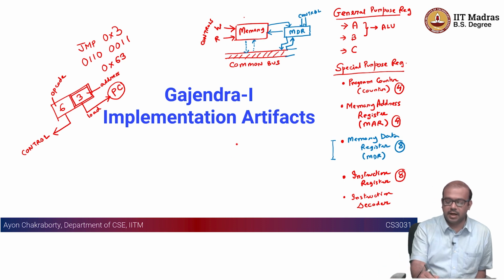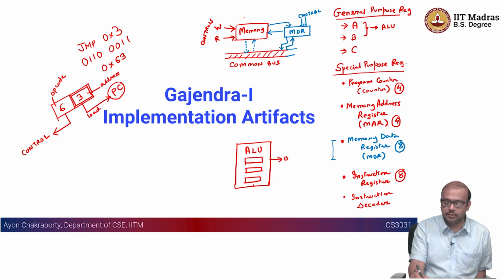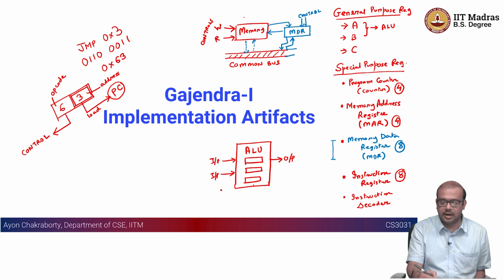In a small block diagram, I am going to show you here. Let's say this is your ALU, and the ALU is going to have some functionalities, right? Addition, subtraction, some logical operations. It is going to have some inputs and outputs. There will be inputs from these 2 registers A and B, at least 1 register, at most 2.